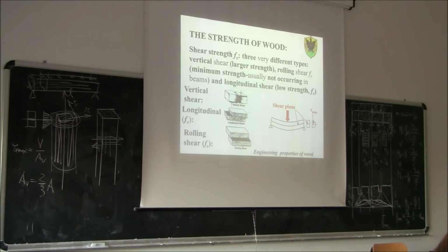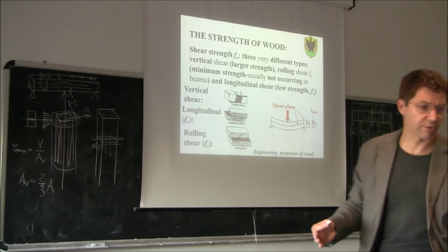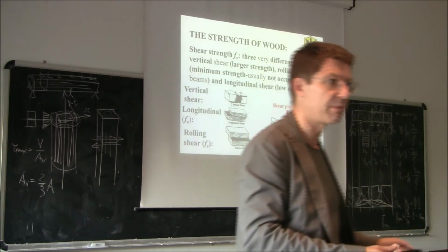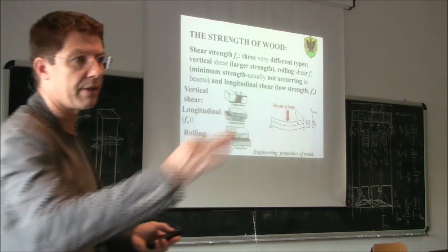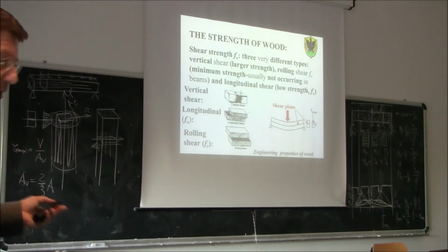I mean, think about, for example, reinforced concrete. The reinforced concrete mechanism was very complex, if you remember well. You remember the crack configuration. In reinforced concrete, you have the load, then first, before you have the activation of the reinforcement, you have some cracks forming. Which kind of direction did these cracks have? Remember? Inclined 45 degrees. 45 degrees.